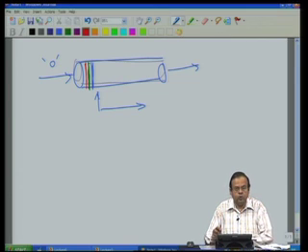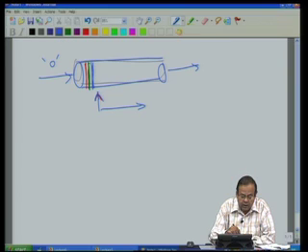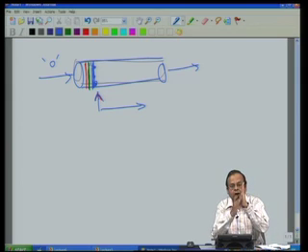But I should also point out that in case of plug flow, there is a complete mixing along the radial direction. What it means is that if you look at this particular plane, then the fluid properties at this radial point, this, they are all same, and so is the case in case of green fluid. So, along the radial plane, there is a complete mixing.